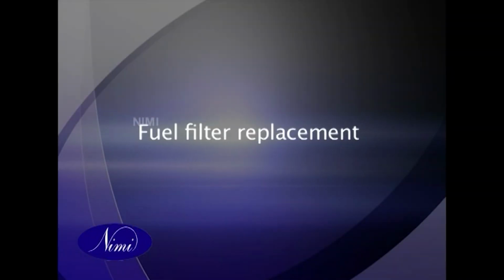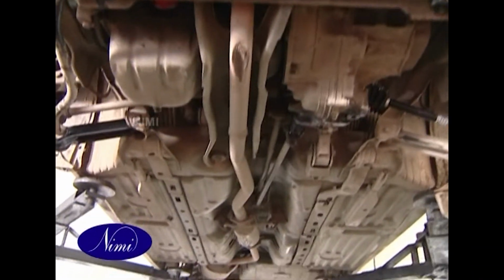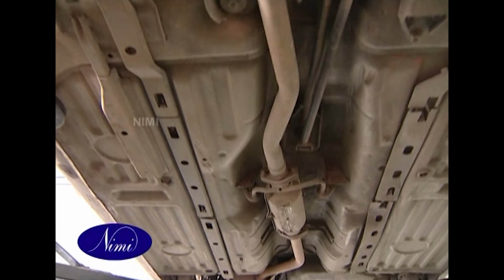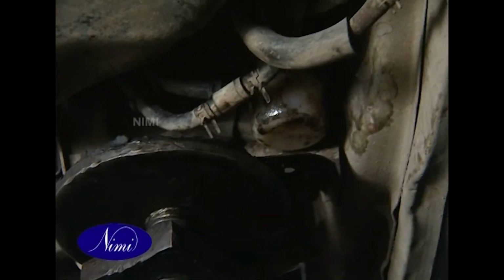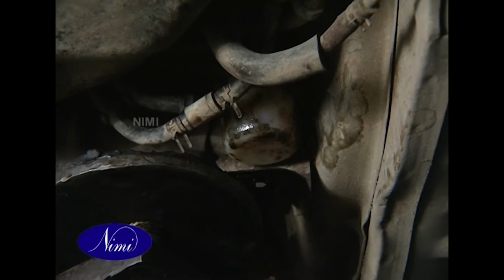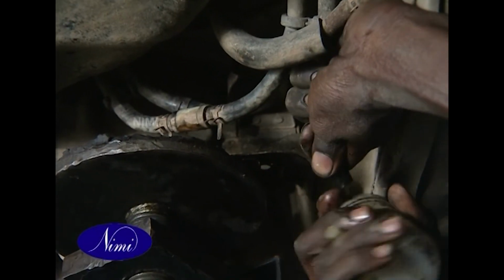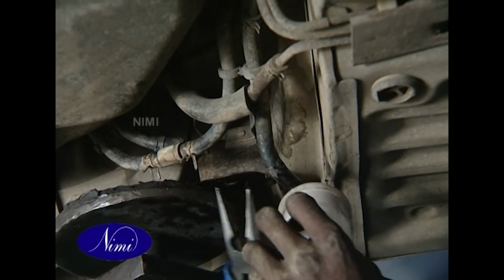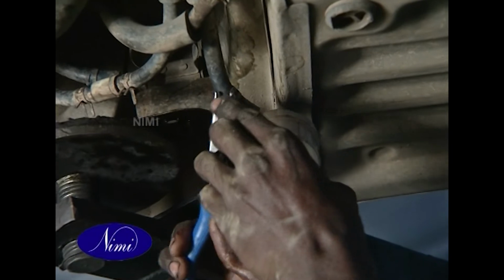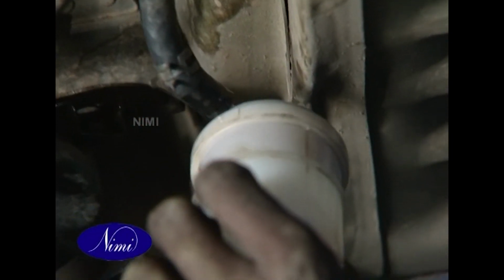Fuel filter replacement. Warning: this work must be performed in a well-ventilated area and away from any open flames, such as gas hot water heaters. The fuel filter is installed in front of the fuel tank inside the left side of the vehicle body. Check for free flow. If blocked, replace the fuel filter with a new one. Ensure that the loose clips are replaced. Also note that the fuel filter is placed in various positions according to the manufacturer. Please refer to the manufacturer's manual.